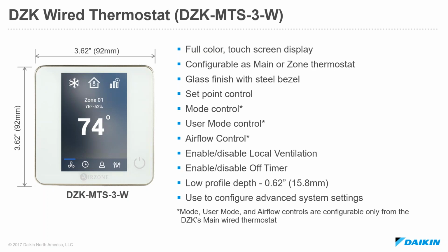This wired thermostat can be configured either as a main or a zone thermostat. So keep in mind again that one thermostat has to be configured as the main thermostat for the DZK. But if you don't want wireless thermostats, you don't have to use wireless thermostats. You can use all wired thermostats, and several of those wired thermostats will be configured simply as a zone thermostat.